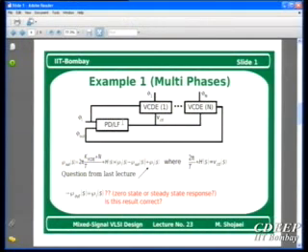And if the phase detector has the entire span of phase shift, we would expect this loop to lock, and if VCTL can handle the amount of phase shift. Suppose the sensitivity of the delay element is too small, so the amount of delay given the entire working span of VCTL, the linear range, is very small. If it is wide enough, then it's fine, because each one of them should generate a phase shift of 2 pi upon n, which is actually 2 pi upon n multiplied by T. That is the time delay it has to provide. If it can provide that time delay, then it will work.